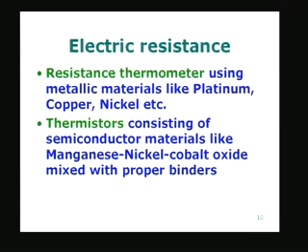Actually, the resistance increases with temperature, and this increase is characterized by a regular relationship, and that relationship becomes itself the basic interpolating formula for the platinum resistance thermometer. In principle, we can also use copper, nickel, and other materials, as long as we standardize them and characterize the relationship between resistance and the temperature unequivocally.